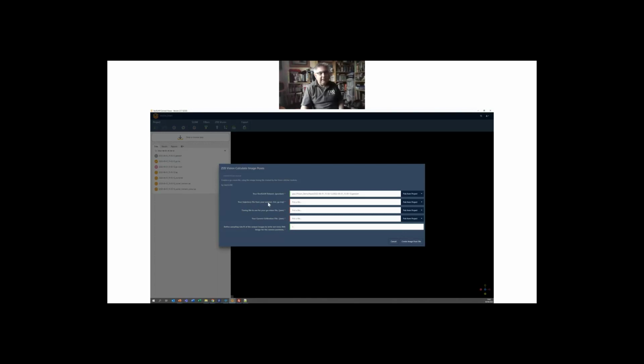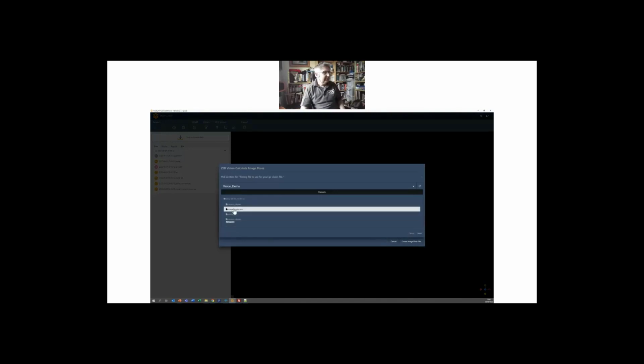The trajectory, clearly we need to know where Horizon was, so we can then interpolate where the camera is. Typically, I use the GeoSLAM. You can use the traj.txt. They're fairly identical. GeoSLAM has a couple of extra fields in, but generally I just choose that one because it's the first one I come to. Then we need the timing file that we've just created in our stitching. Again, image timings.json.